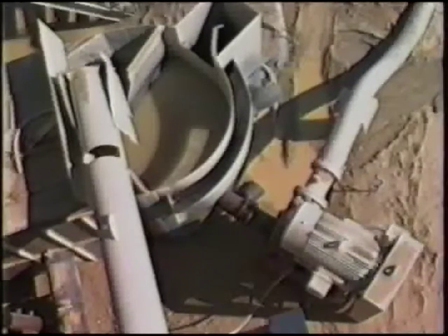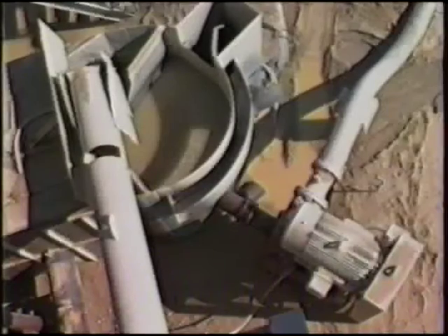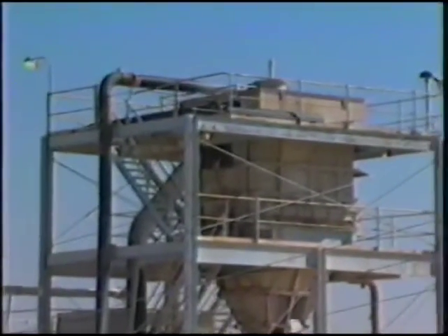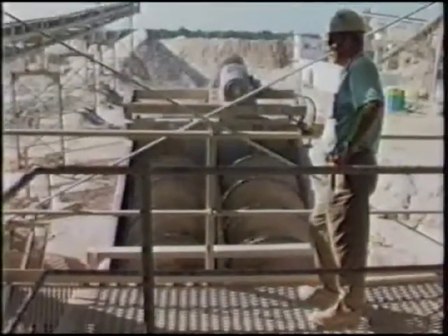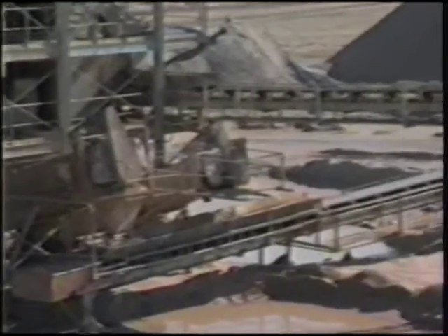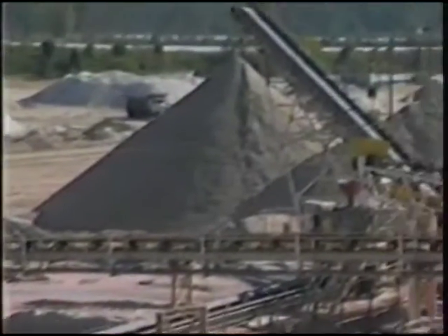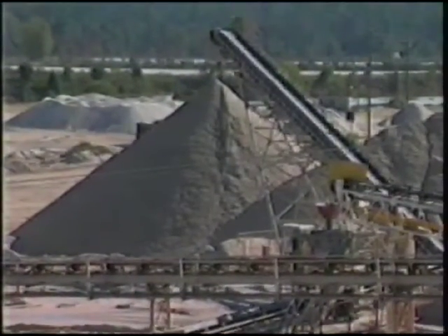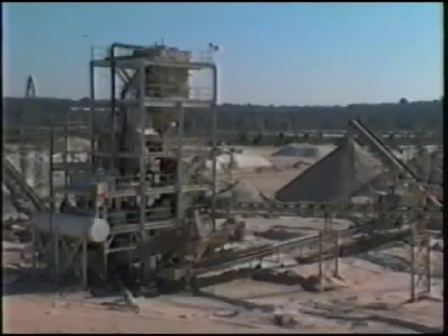The fine aggregate from the barrel screen is collected in a sand sump and pumped to the top of the plant for sizing. Various types of water classifiers are used to separate the fine aggregates into the proper sand grades. Standard products, such as grading A concrete and masonry sand, are conveyed to the stockpiles. This plant also makes several specialty products, such as golf course bunker and greens mix sands and filter sand.